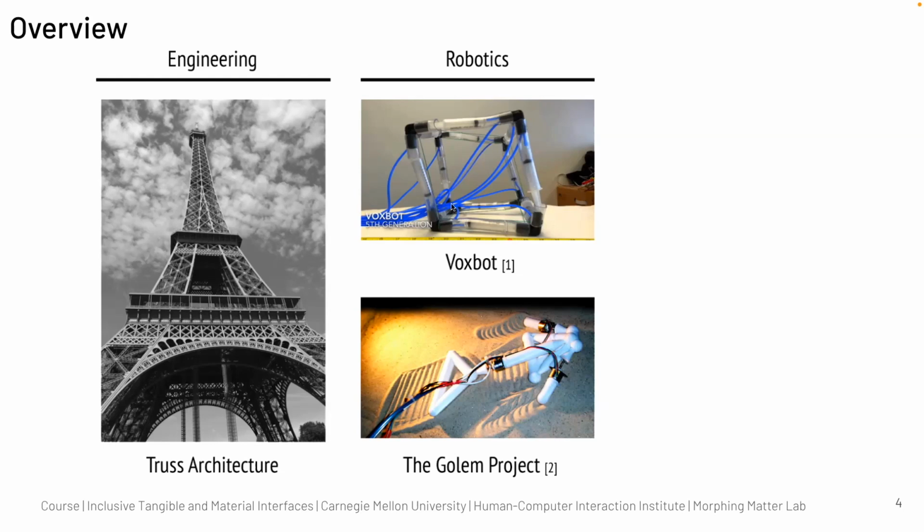And this is another prototype that you can see. One part of this structure is that there are a lot of linear actuators. Each beam is a linear actuator. If you give pneumatic power, it will elongate, otherwise it will contract. If you want to control each individual beam, you need a lot of tubing to connect it, so it's quite a complicated setup.